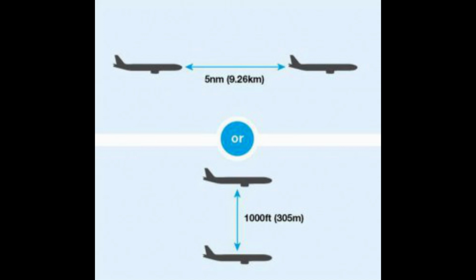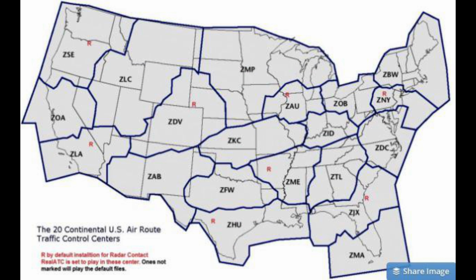The catch point indicates where a flight ends a segment of NRR and joins published arrival procedures, preferred IFR routing, or other established routing programs. The HAR Phase 1 expansion airspace is defined as that airspace at and above FL 350 in 14 of the western and southern ARTCCs. The airspace includes Minneapolis, ZMP; Chicago, ZAU; Kansas City, ZKC; Denver, ZDV; Salt Lake City, ZLC; Oakland, ZOA; Seattle Centers, ZSE; Los Angeles, ZLA; Albuquerque, ZAB; Fort Worth, ZFW; Memphis, ZME; and Houston, ZHU. Jacksonville, ZJX, and Miami, ZMA, are included for east-west routes only.